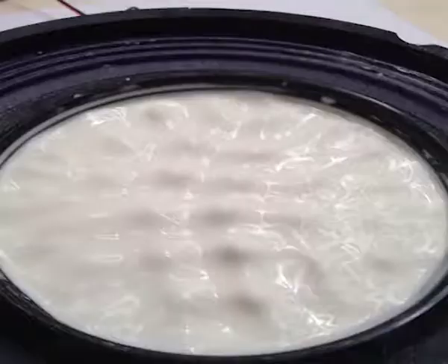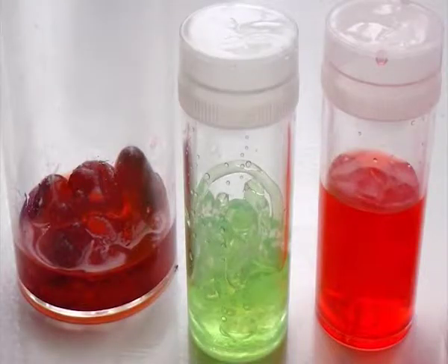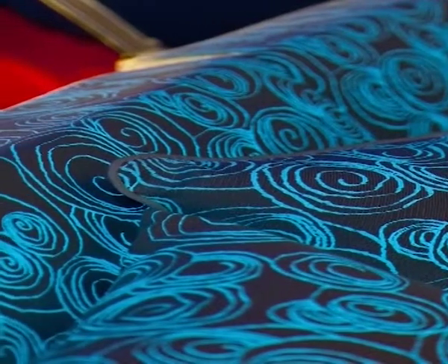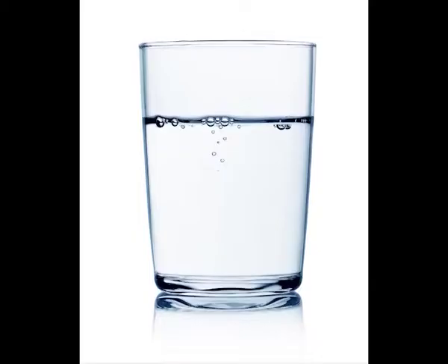To prepare the printing paste, a thickening agent is added to a limited amount of water and the dye is dissolved in it. Earlier, cornstarch was preferred as a thickening agent for cotton printing. Nowadays, gums or alginates derived from seaweed are preferred because they are easier to wash out and do not themselves absorb any color and allow better penetration of the color. Most pigment printing is done without thickeners as a mixing up of resins, solvents and water itself produces thickening.